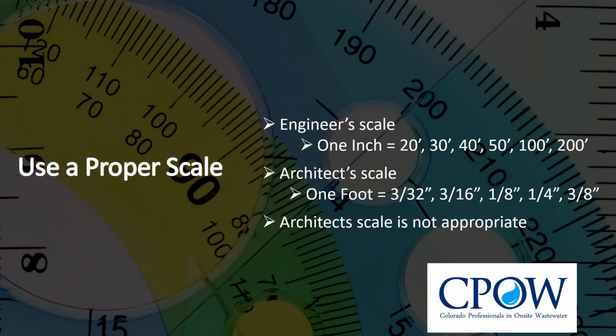The engineer scale is the industry standard and preferred method. Do not use an architect's scale. You cannot make up a scale. For instance, 1 inch equals 15 or 1 inch equals 70 feet is not a scale. Depending on the distances between components, most commonly used scales for record drawings are 1 inch equals 20 feet, 30 feet, or 50 feet. For larger parcels, 1 inch equals 100 or 200 may be used. Use what scale can be used to accurately identify the location of all components and still fit on the drawing.